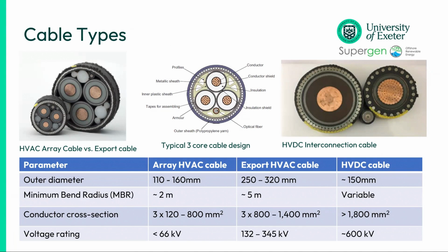Yeah, probably all of those. The metallic sheath is exposed, definitely, and it depends a little bit on cable construction what's the most vulnerable part. But one leads to the other. So if the metallic sheath fails, your insulation will break down. So that may well be the first layer in trouble.